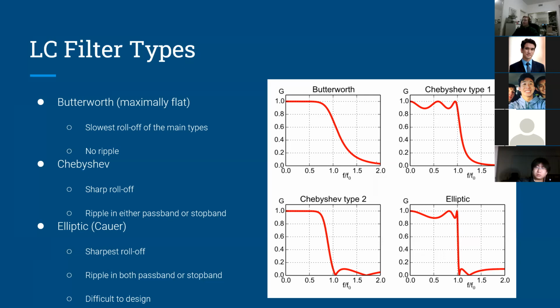And it kind of looks like an RC filter. So in the passband, it looks pretty flat, and then there's a roll-off as you go to the stopband. But the key characteristic of a Butterworth filter is that there's no ripple anywhere. It monotonically decreases as frequency increases. And you can see that's definitely not the case with the other ones. The problem with it, though, is that it has the slowest roll-off of these filters for a given filter order. We have a comment.